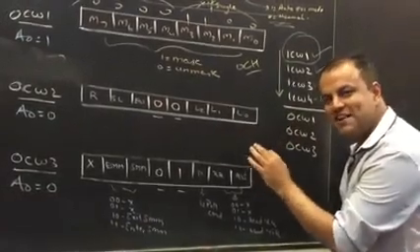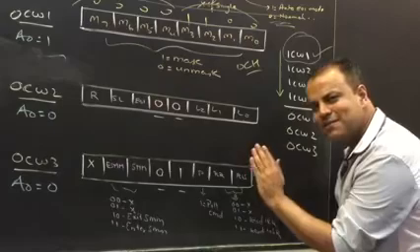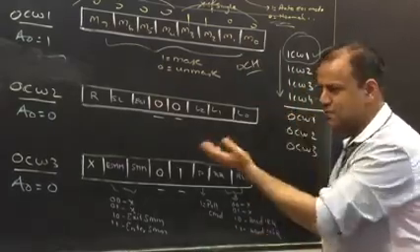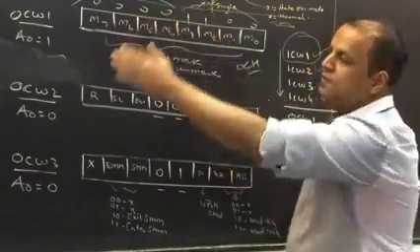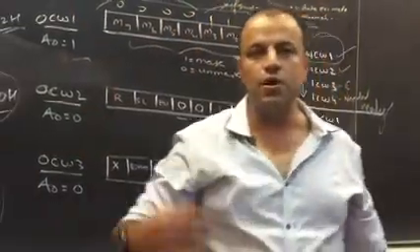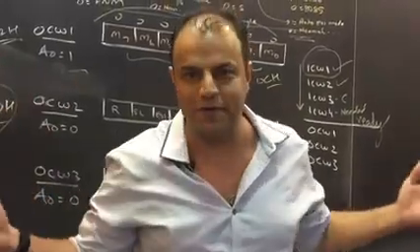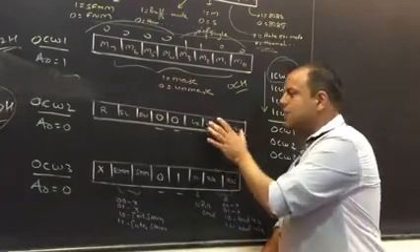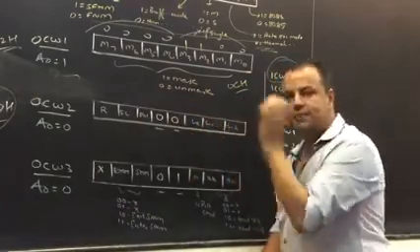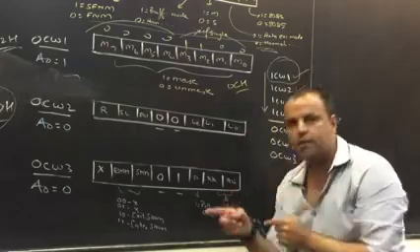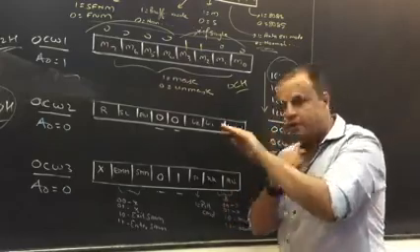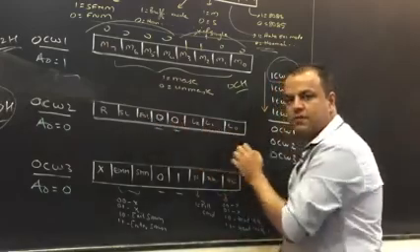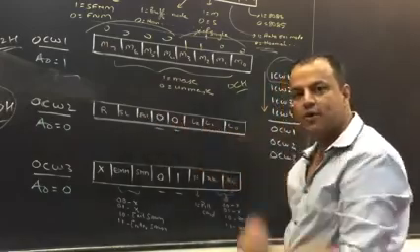Did you instantly understand how advanced this command is? This is 4 levels higher than what you're learning. To be very frank with you, this is not student stuff. With all of the other commands, whatever you do, you are affecting the whole chip of 8259. You're deciding how 8259 will work. But in this command, you can decide a different behavior for every interrupt line. You can have IR0 working in a different way, IR1 working in a different way, and so on. Per line, you can give this command and specify exactly how you want every line to behave.